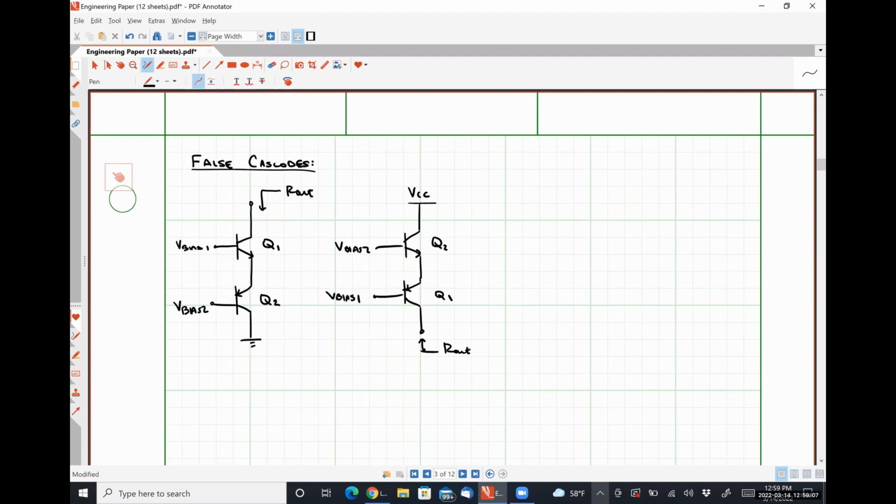If we did the math here, we would find with IC of 1 milliamp, beta is 100 and VA is 5 volts, just like all the other examples that we've worked out thus far, our output resistance here would be roughly twice R naught 1. So it does increase the output resistance to some effect, but it's even smaller than just using an actual small resistor to degenerate. Okay? So these are here specifically to trip you up and to do a bad job. You should never actually use these. Okay, I just wanted to talk specifically about why you cannot.